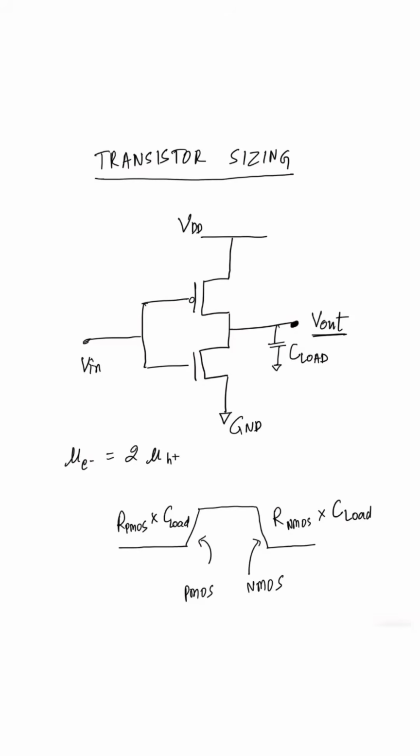This is a core VLSI concept and one of the favorite questions in interviews. In our designs, especially for clock network or clock cells, we want the rise time to be equal to the fall time because otherwise it can cause issues with respect to duty cycle distortion or min pulse width violations, which we will discuss in later videos.